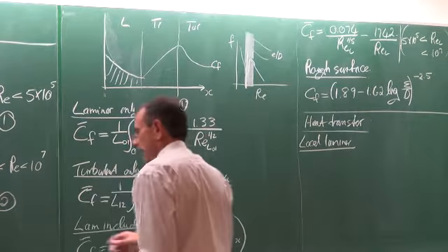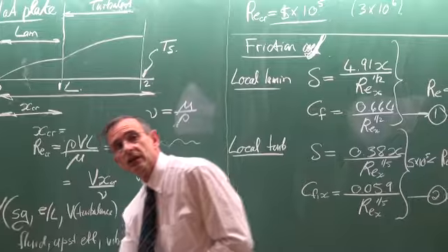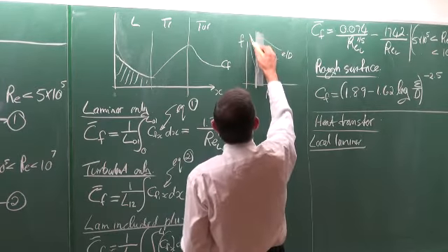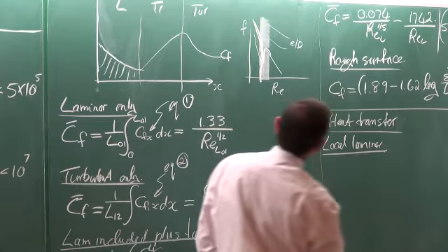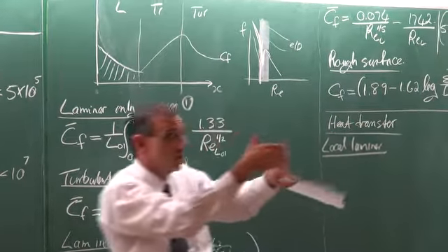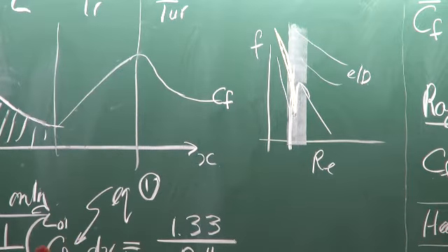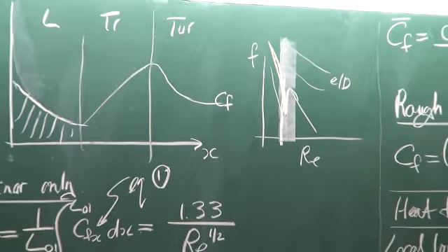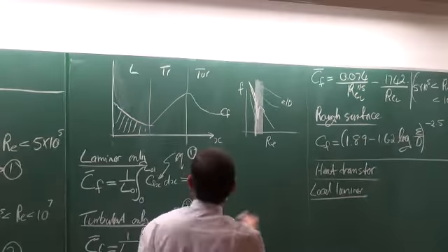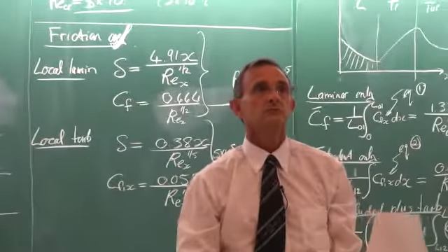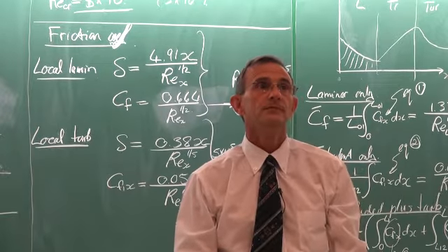All our latest experiments are showing that this should be modified, where the gray area actually does something like that. Which means that the rougher the surface is, the quicker the transition will occur from laminar flow to turbulent flow. So in general, this area would become shorter as the roughness increases. To answer your question?